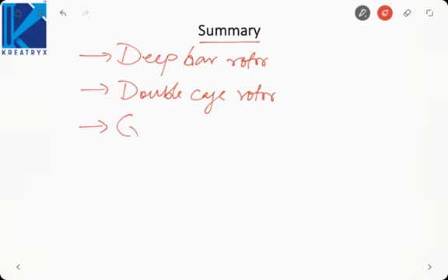Then we studied crawling, in which the induction motor attains a stable position at a very slow speed, due to which slip is high and the rotor current is also high. Then we studied cogging, in which the rotor fails to start due to the strong alignment force between stator and rotor if the rotor teeth are a multiple of the stator teeth or equal to stator teeth.